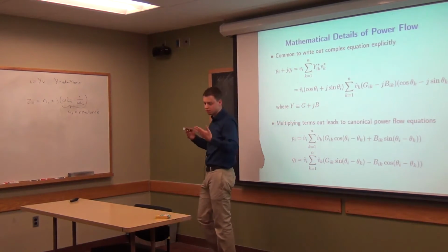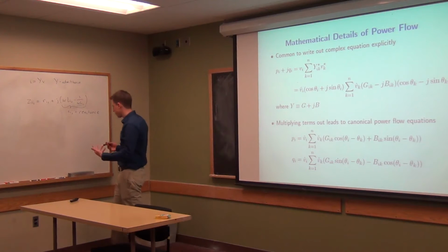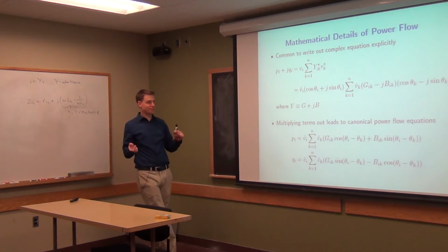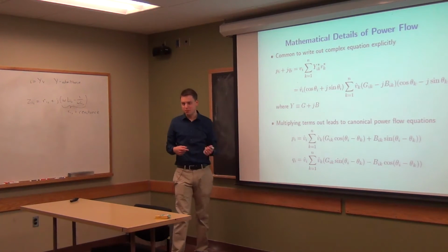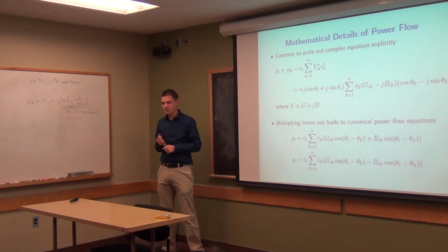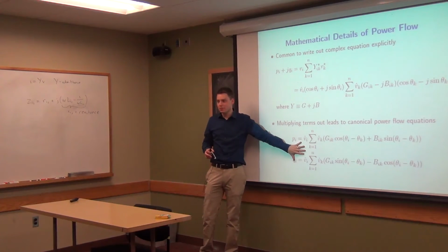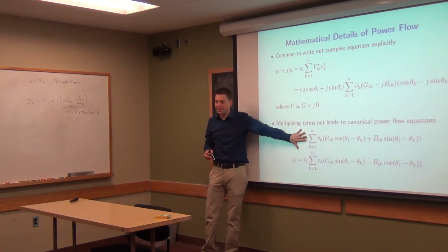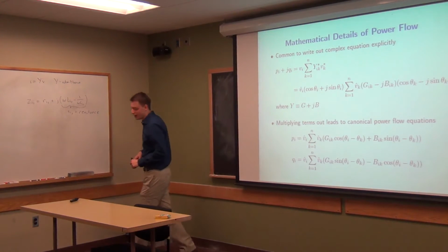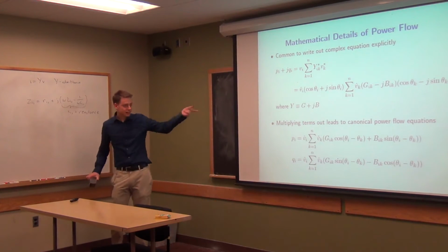That's just how people often write power flow. When we actually go to solve it, though, it'll be much nicer to go back to the old form, for reasons of computing these derivatives and everything like that. You can imagine the Jacobians here get pretty nasty, though plenty of people do write them this way, or in a way like this, which is just horrendous. So let's talk about why this holds.